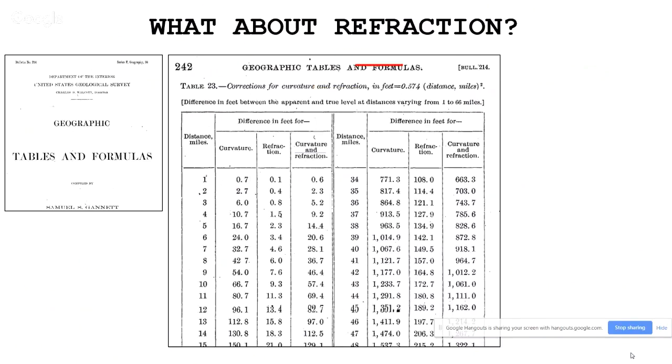And the 0.57 is with refraction considered. So think about it. 8 inches is 0.67 feet. So 8 inches times the mile squared, it's 0.67 feet. It's a tenth less when you consider refraction. So it lessens it, you know. And there's the example just using 10 miles.